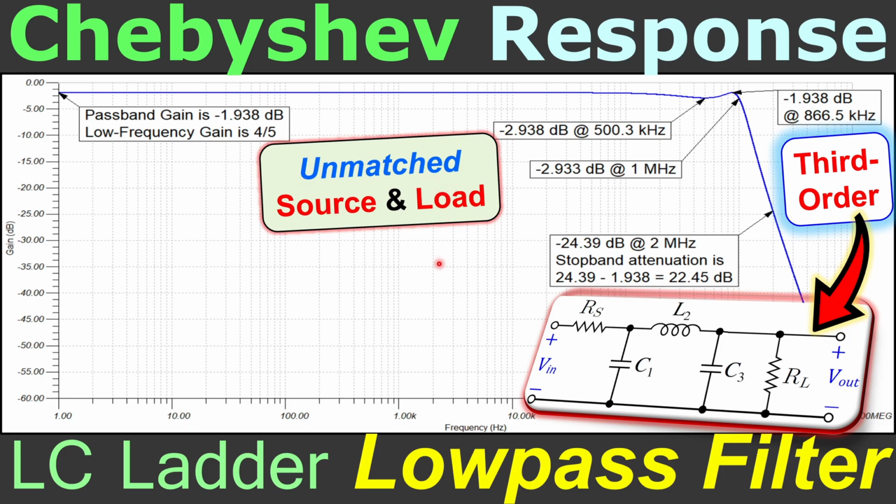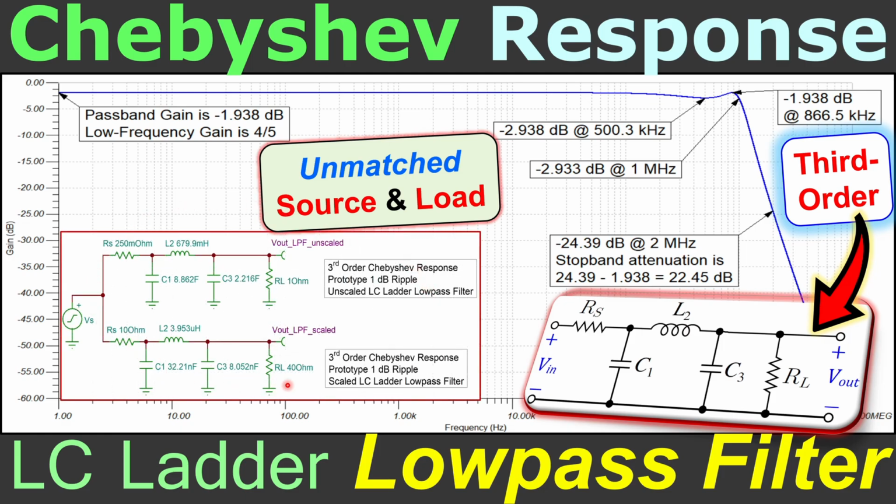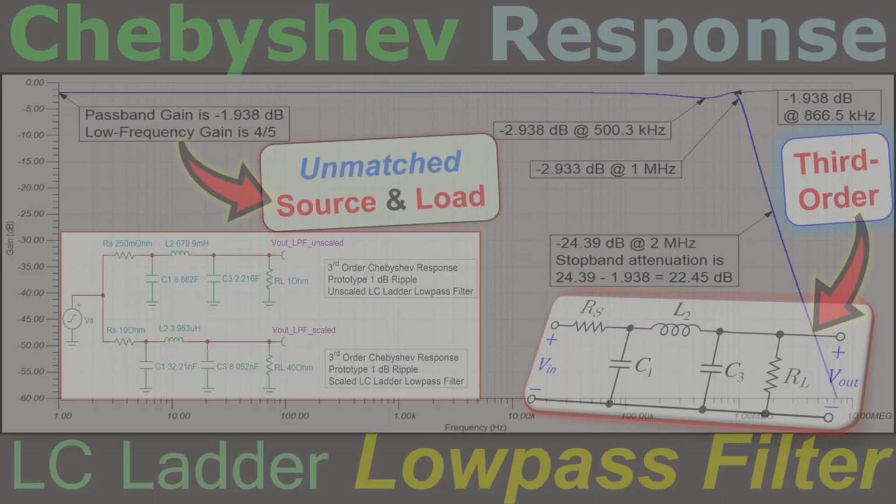We have seen in the previous example about the Butterworth response where the source and the load were not equal, so they were unmatched. And this is the situation for the Chebyshev response to illustrate the concept also there. So we will see how we can calculate the component values for this circuit. And we will see how we can also calculate the low frequency gain for this specific situation. Of course, we will work out everything in our calculations step by step and also verify these in SPICE simulations.